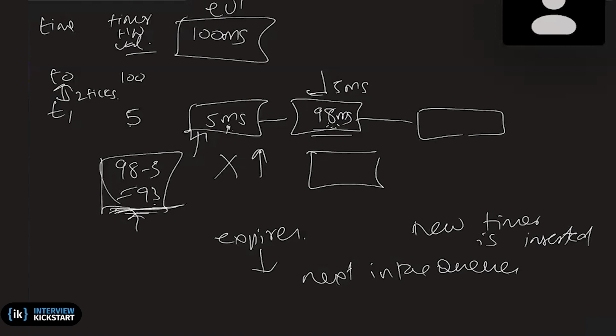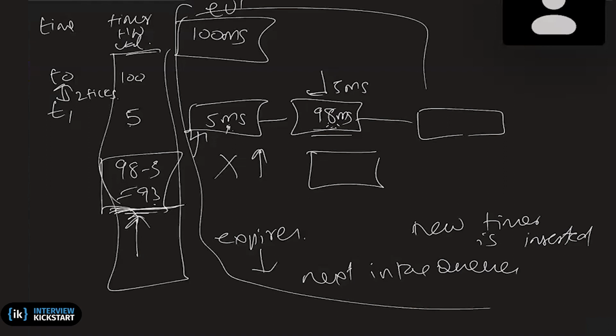Did it clarify? Yeah, I'm still thinking about the difference with the fixed one actually. No, in the fixed one, the timer value is fixed. The timer counter value is like 10 millisecond or whatever you program it. Here it is variable. That's the whole essence of the dynamic timer. You can think of the rest of the things as detail. Think of this timer counter value: it is variable. Whenever a new event is scheduled, that remaining time is programmed in the hardware counter. That is for the head of the queue. But you need to keep track of all pending events, so there is a queue. So the timer will fire only after this count has expired.